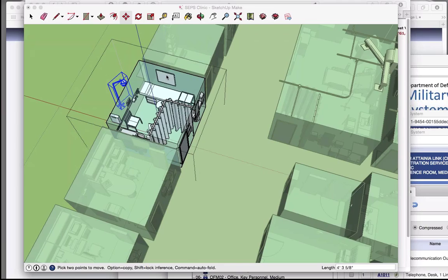These are the owner's requirements with a ton of data in them about the type of room, the type of equipment, the attributes of equipment, and even down to finishes and things on the DoD side. There's other attributes about the rooms, and BIM is really great at processing a lot of data. And if you have a control model that says here's the owner's requirements, and you're designing the model, whether in Revit or Onuma, you can start doing a comparison from one to the next.